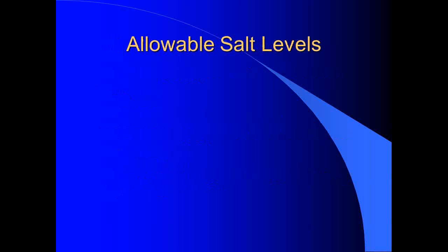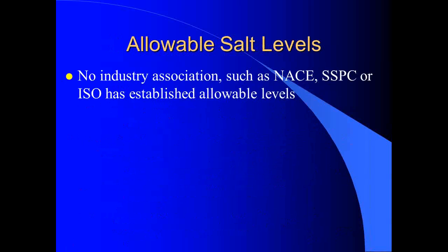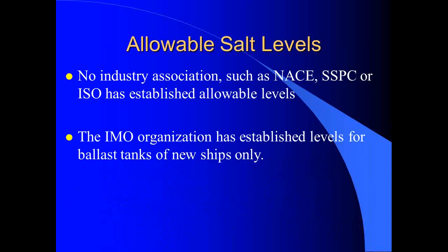Switch and go on to allowable salt levels. No industry association such as NACE, SSPC, or ISO has established allowable levels. A lot of people have tried. The IMO, International Maritime Organization, has established levels for ballast tanks of new ships only. So it's kind of a single use. Eventually, they're going to require it for ballast tanks of all ships, but it's going to be strictly on ballast tanks, nothing else.